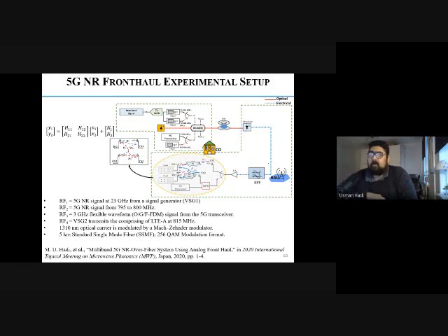So what we are doing in a very recent work that we have started is that we realize an analog ROF. We use fiber wireless, which is actually MIMO, multi-input, multi-output antennas. We have fiber, which is the optical communication like radio over fiber, and then we have a wireless medium. So we are trying to mimic that. Once you have the fiber up to your home, then from that part of your broadband, you use Wi-Fi or whatever at the receiver end, at the user equipment side. So we are connecting the fiber with the wireless medium.